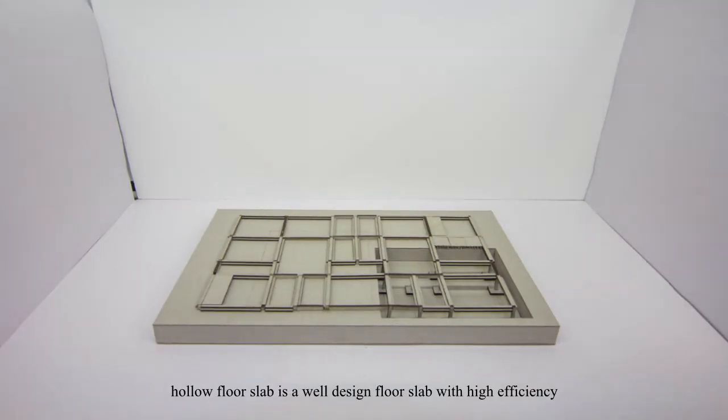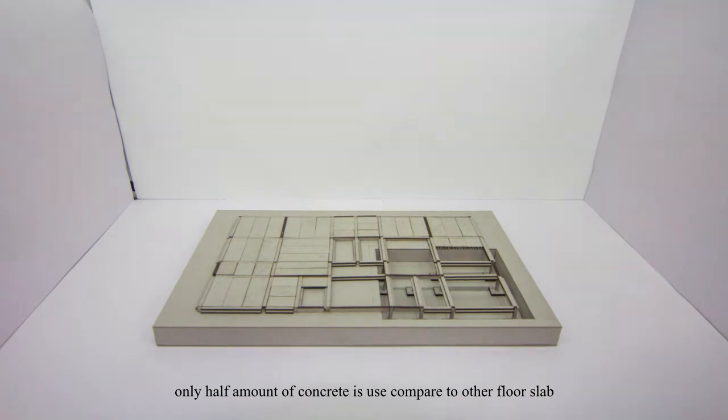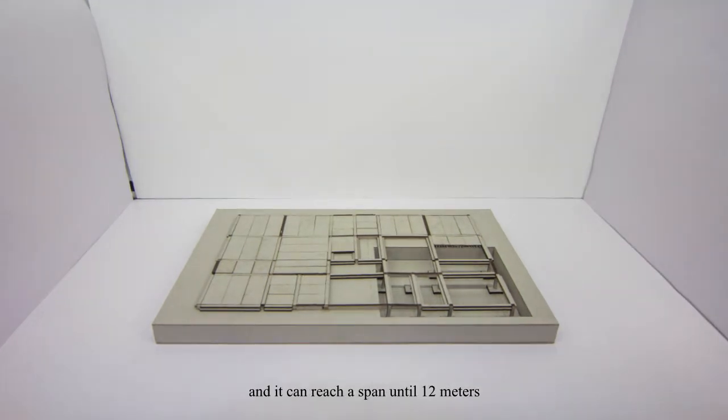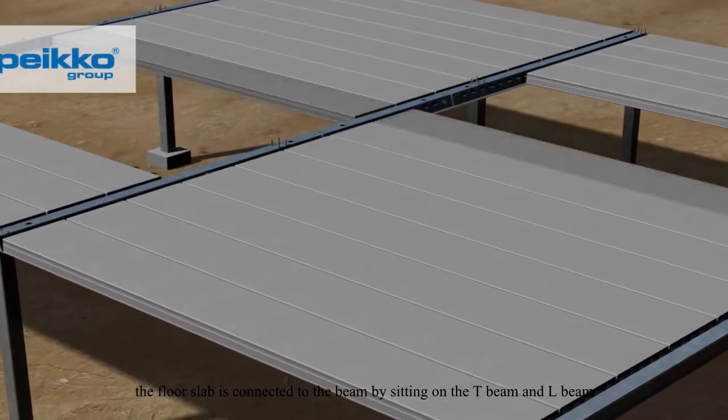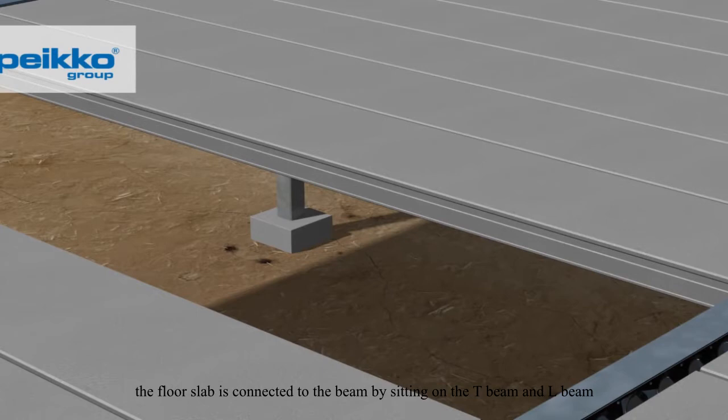Hollow core slab is a well-designed floor slab with high efficiency. Only half the amount of concrete is used compared to other floor slabs, and it can reach a span of up to 12 meters. The floor slab is connected to the beam by sitting on the T-beam and L-beam.